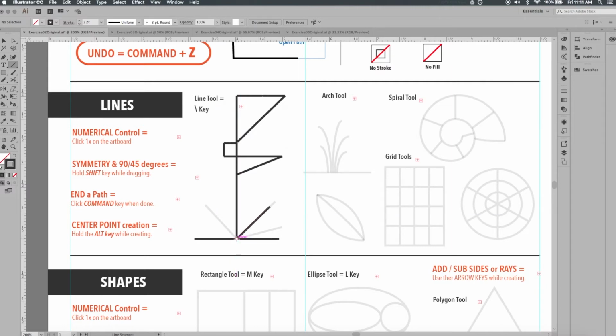Let's go ahead and do that for this side as well. So I'm going to click once, and instead of 45 degrees, I'm going to come right over here, and let's try 135 degrees for this angle. So it's basically 45 and another 45 this way. And let's do it at 1 inch, and then I'll click OK. And there you can see we have another line going that way. We'll go ahead and just freeform one more line right over there.